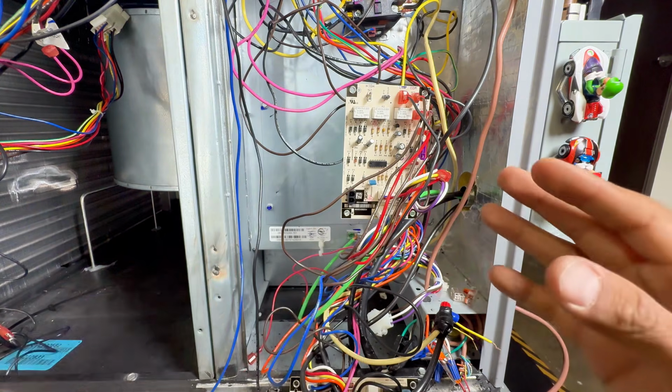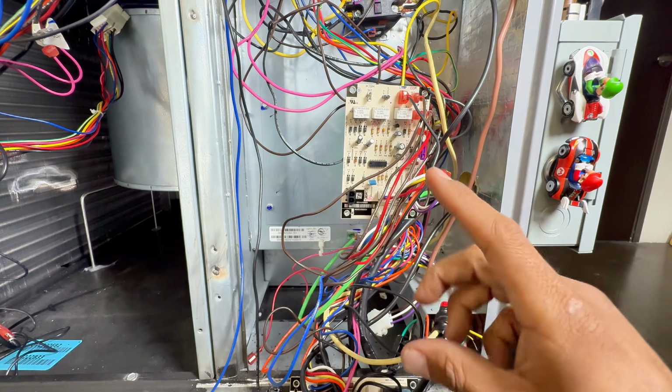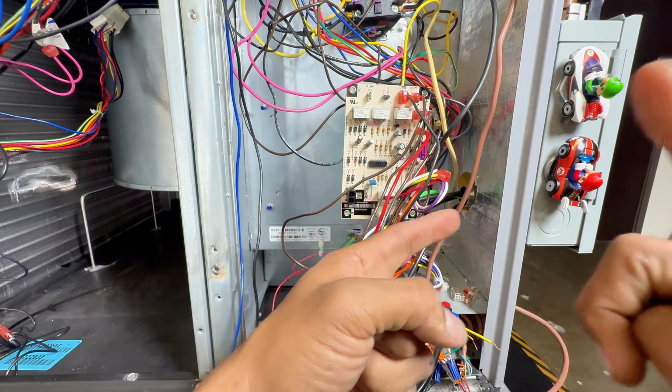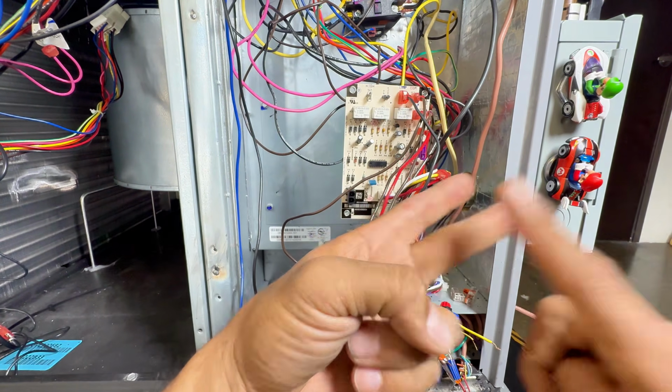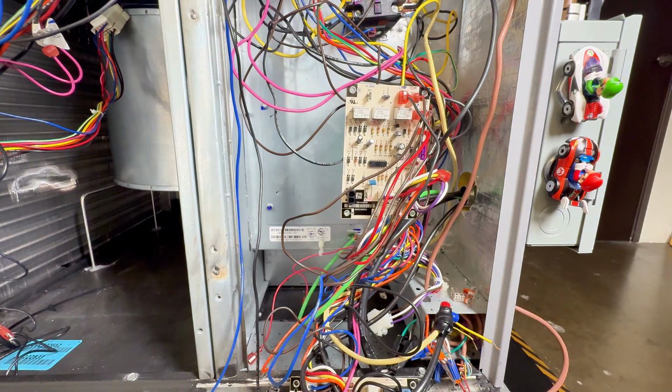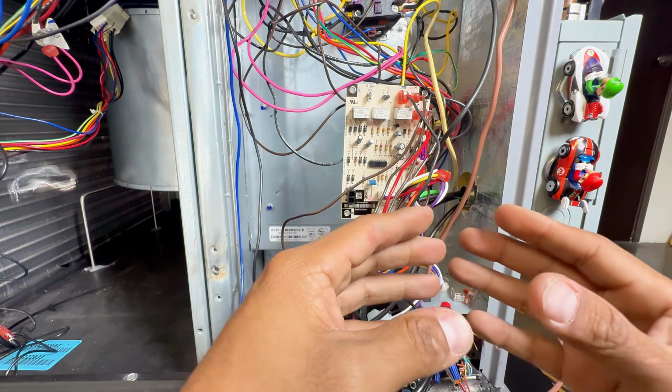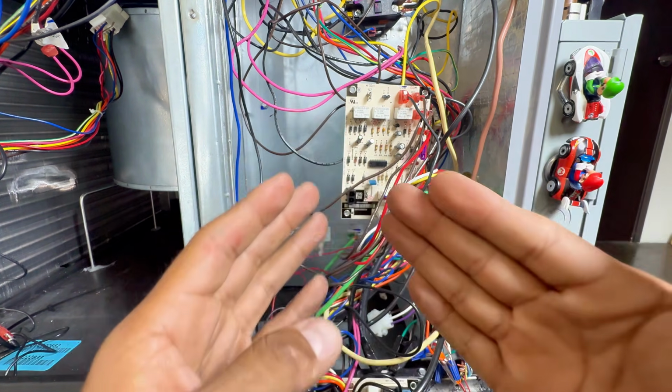and turn on the components that take high voltage. That's all we're doing. So in this case though, we're working with the cooling, right? A heat pump. So we need to send power to my reversing valve and my compressor, okay? So by now, hopefully the previous clip kind of gave an idea how the 24 volts travels.